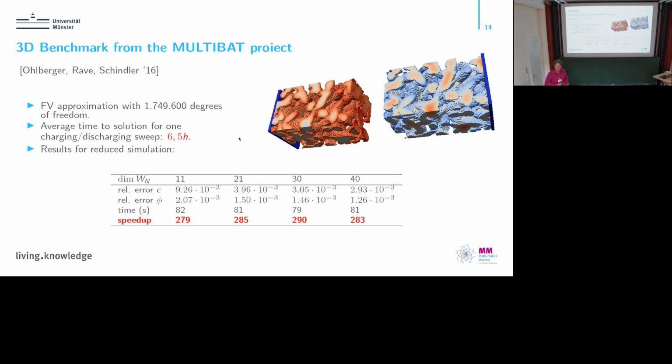This is very nice, and the engineers are happy if they have this reduced model and they can play with it. But it comes at a very high cost, because this offline phase is really expensive. You need to solve time-dependent problems of that size multiple times. You need to keep all this in storage, which is a mess. And this is often neglected when people talk about reduced basis methods, that there is this enormous offline cost that comes with it. And this is the triggering point if you go towards optimization problems.